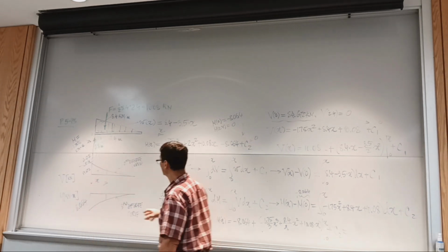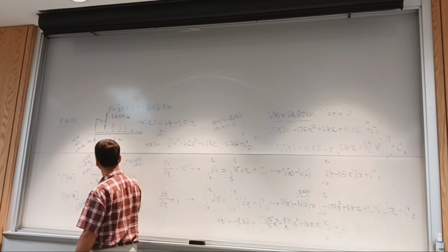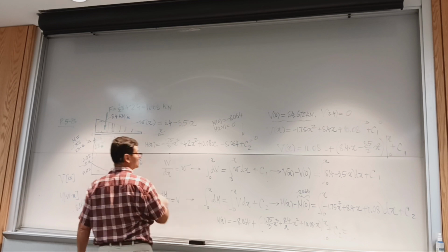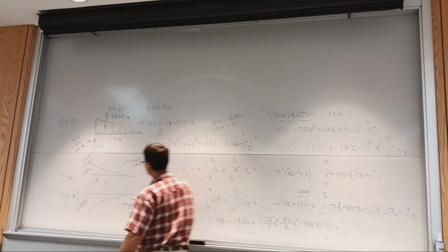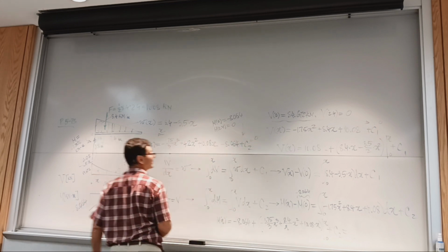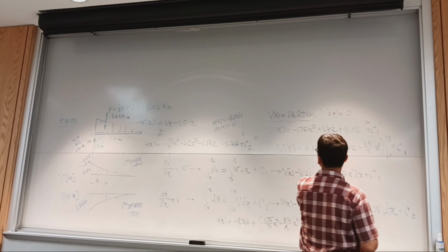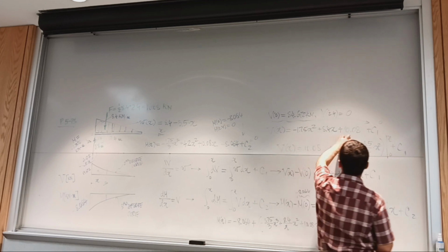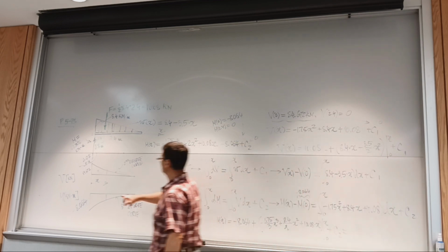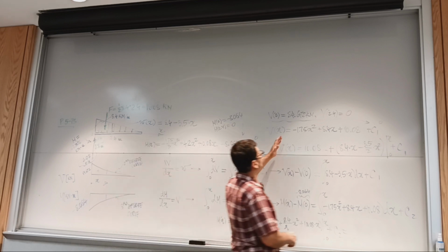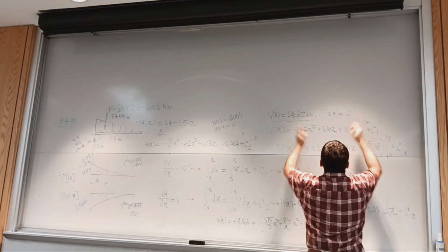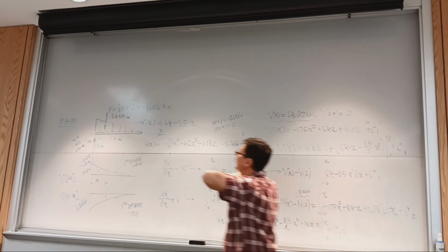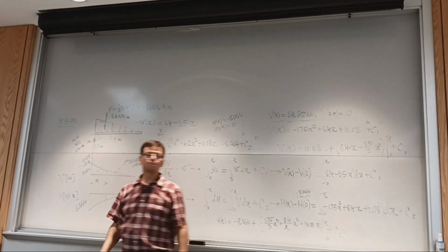If you have the moment equation, of course, you just put x equals 1.2 in the moment equation, and it gets you the moment. But otherwise, you can use area. So this was verified. And to find the bending moment at the middle of the beam, I need to integrate v between 0 and x equals half of this. This is 1.2. This is the way of doing it.